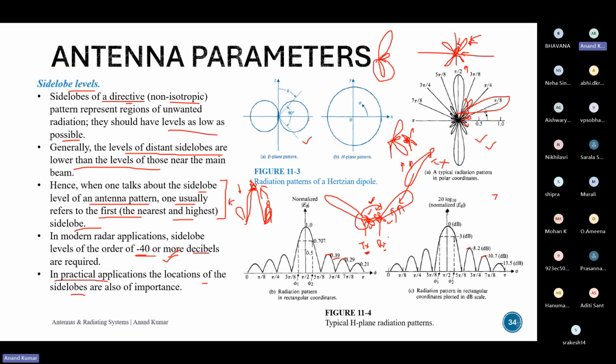For example, if this is a side lobe over here, which is greater than minus 40 dB, but it is in a direction which is not relevant, you could just be satisfied with this, as you know for sure that in this direction you probably won't have any devices placed. You only have devices in this direction. So it's fine. You can just ignore the back lobes and the side lobes at the rear side of your transmitter and be okay with it because it won't affect your performance.